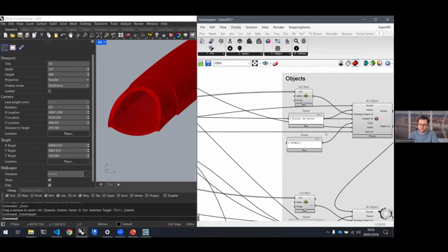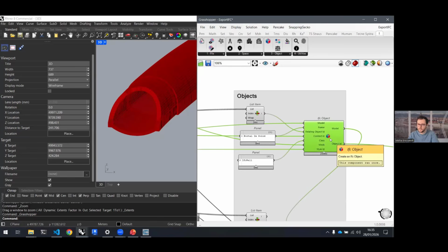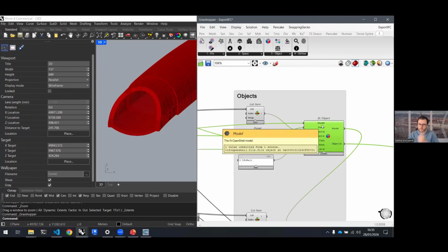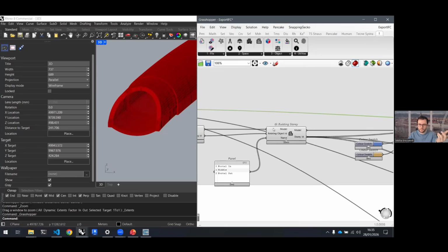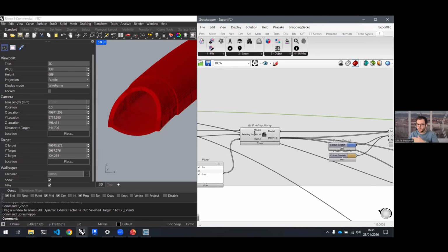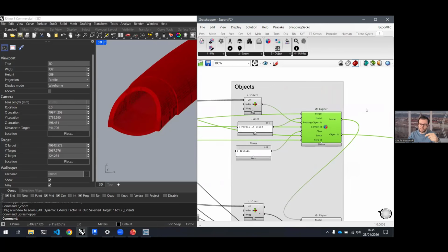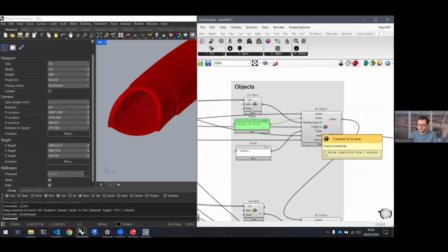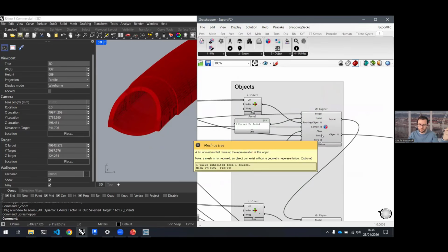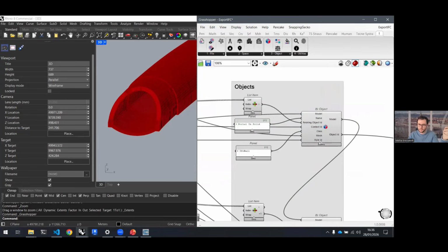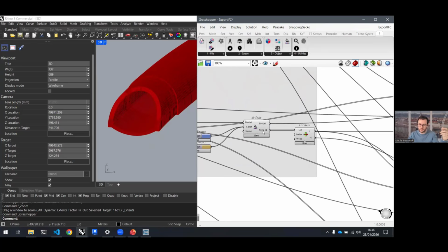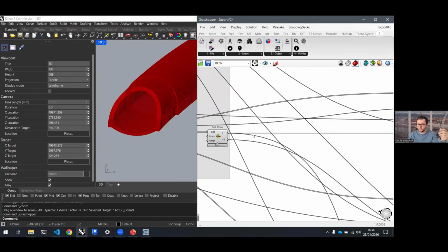And then we have this IFC object. The model is just being passed between each component so that it's updated each time. Then you have a name that we call the porcelain solid. The context is the one we created at the beginning. The class we just decided is an IFC wall. The mesh is the mesh we took from the model. And the style ID is just the step ID of the style we created here.